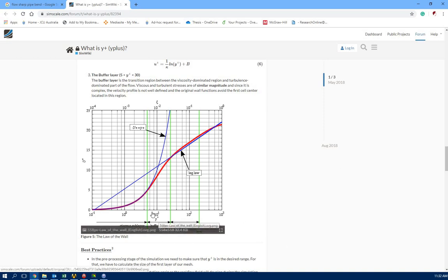For example, if it's less than, for example, 5, 6, you can capture more details of your parameter close to the wall. So we usually refine our mesh close to the walls or close to the area we have sharp change to capture more details. Okay.